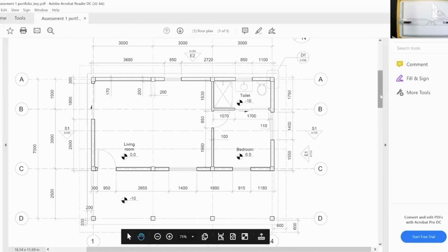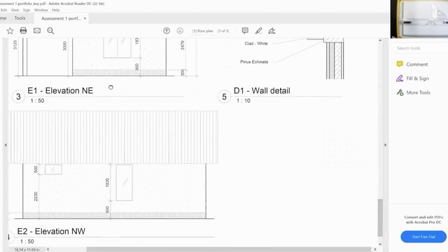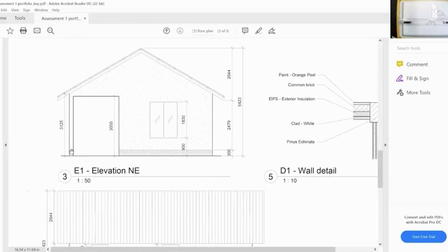All right, so let's go back to the elevation drawings, and we can see here what we just talked about. The column, a void, the segment of wall, our window, the bedroom window, and another segment of wall. Our roof divided in 2 slopes, right in the middle here, with 600 millimeters of eave to the right and to the left.